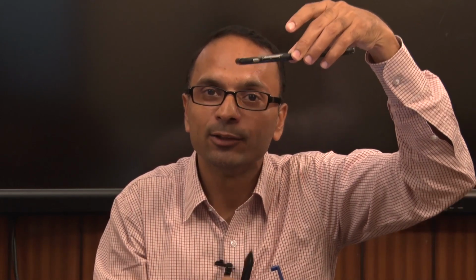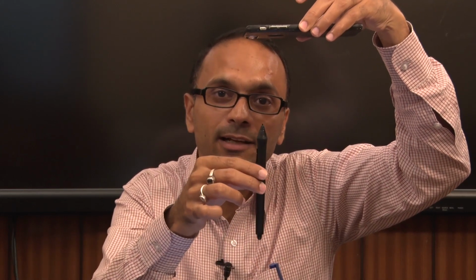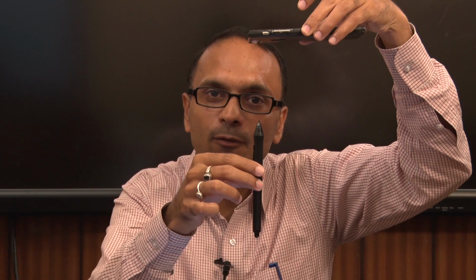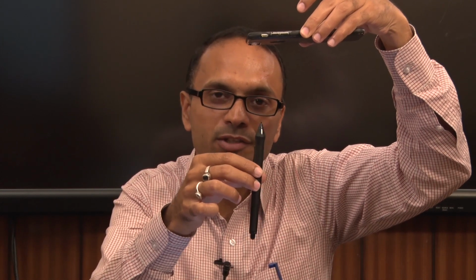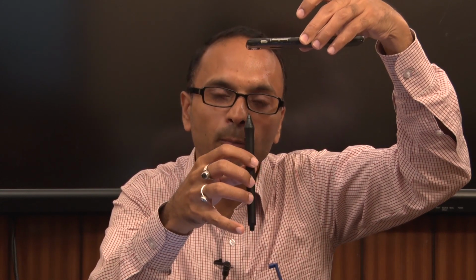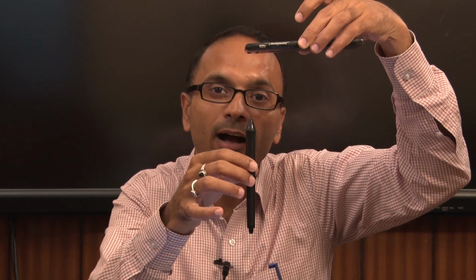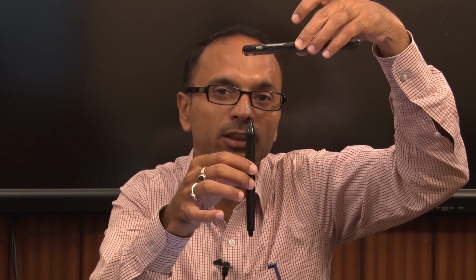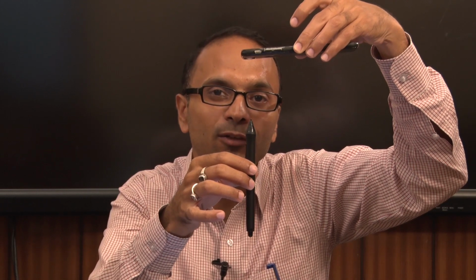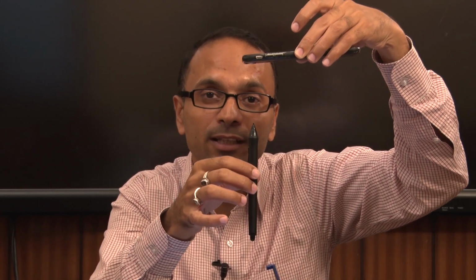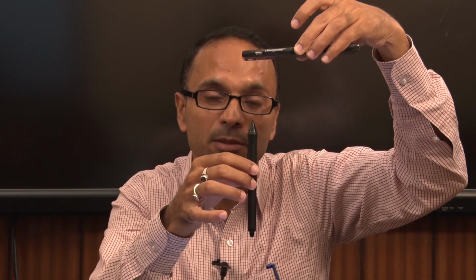Try to do these experiments yourself. This is very simple because you have the mobile camera with you. Assume that the mobile camera is mounted in an aircraft and your hand is an aircraft. So, now you are acquiring the photo of a certain terrain where this is a building. So, now if you take the photograph in which this is appearing, you will find out the bottom and the top of the pen are appearing at different positions, and the difference from the center, which I am assuming is the principal point of the photograph.